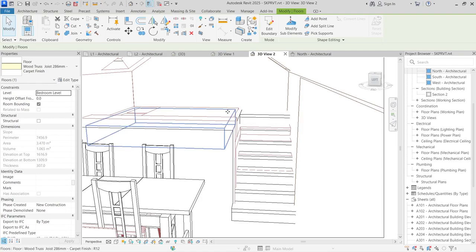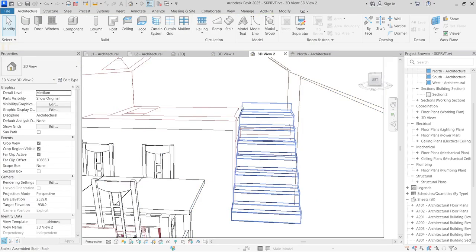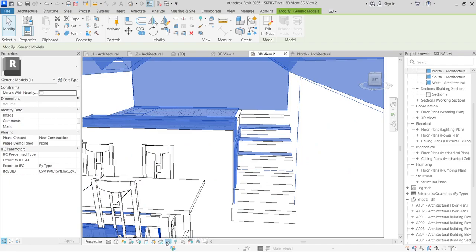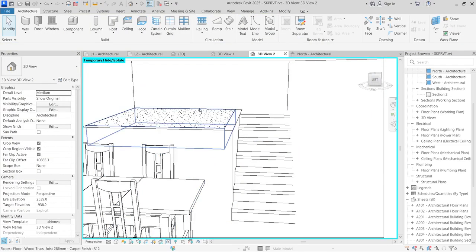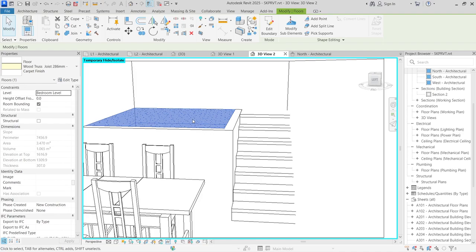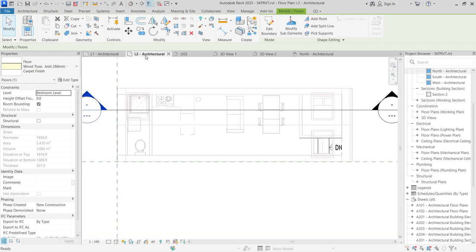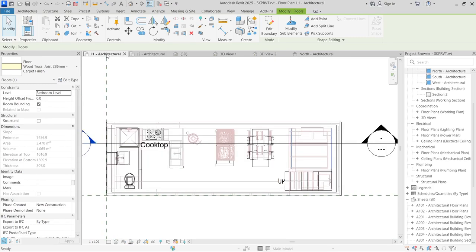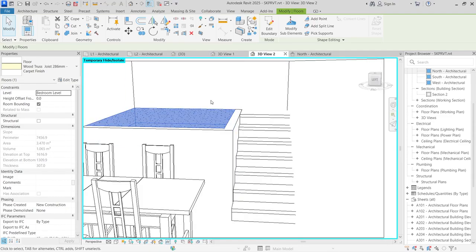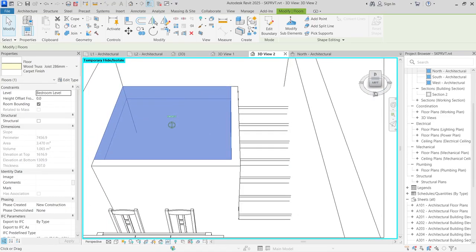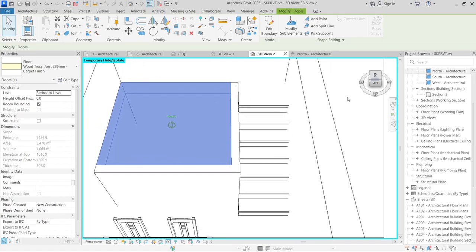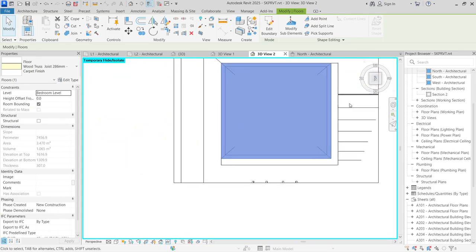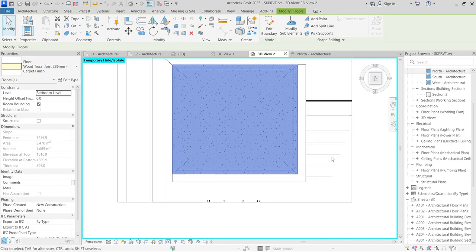We have to now align it properly. So we're going to hide the SketchUp model now and just focus on Revit. We're going to select the SketchUp model and just select the pair of glasses and hide that element. So we see the floor joist now. I can move over to, or we can use the 3D view to actually do this. Just go over to the top just to make sure that everything is as it should be.